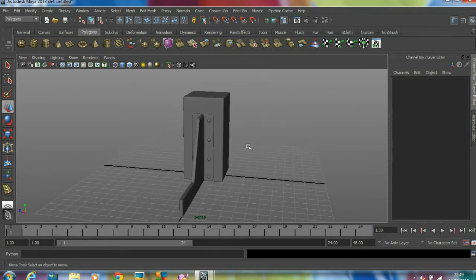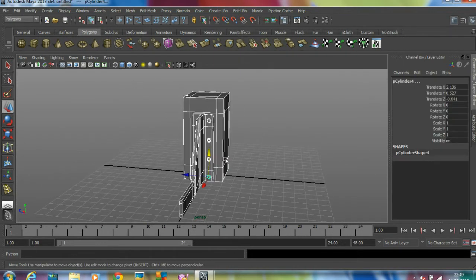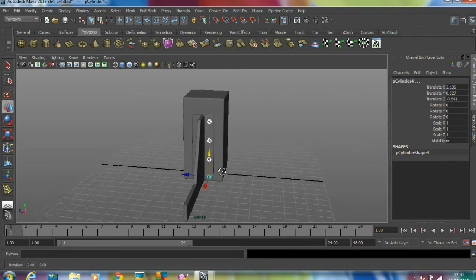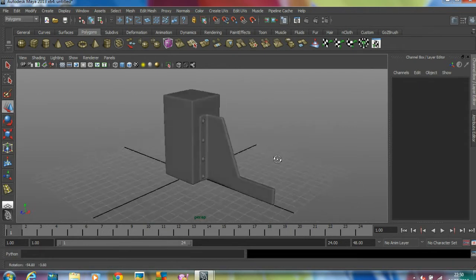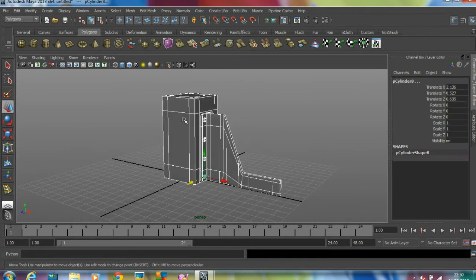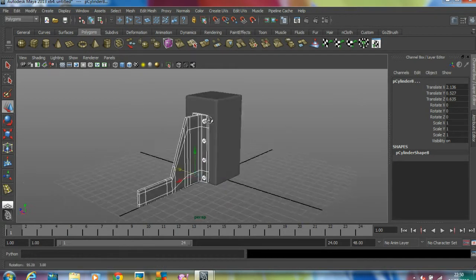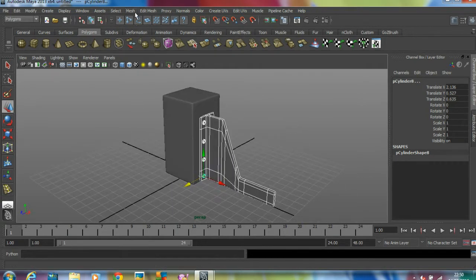Right. Now drag and select all these bolts. But when I'm dragging, I can select all these things. So hold Control to deselect all these objects. Control D. Pull this side. Now drag and select everything, hold Control, deselect the main block, so you can select this whole crank or whatever.